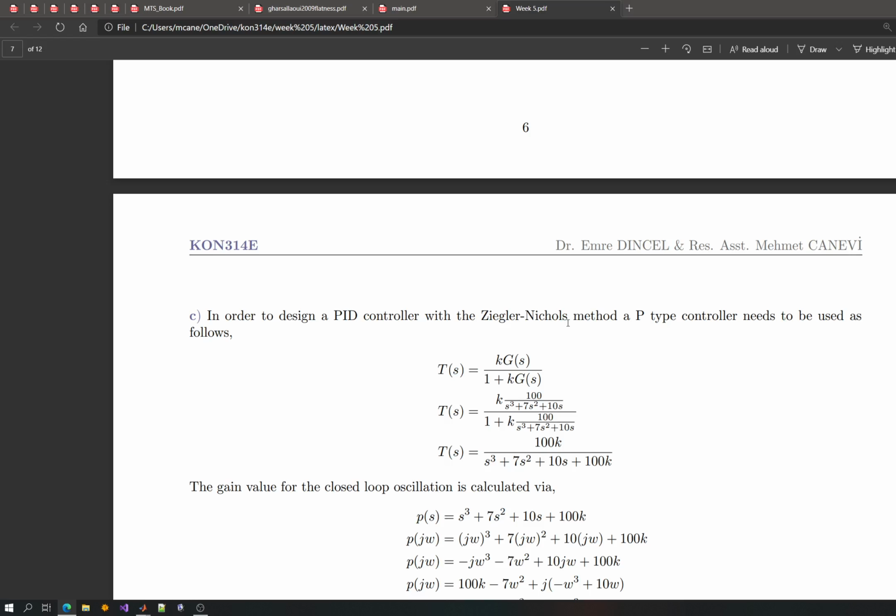And also, you need the frequency, or even the period, the time period of this oscillation signal. So you need the critical gain, which is driving the system in the closed loop to oscillation, to marginal stability, and the frequency of that. So basically the crossing point on the j omega axis. These two parameters, K and Pu, will then be used with formulas that give you PID parameters directly. So that's it. There's no tabulation, no pole zero cancellation, nothing at all.